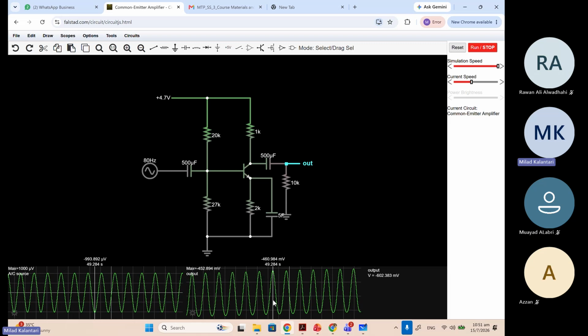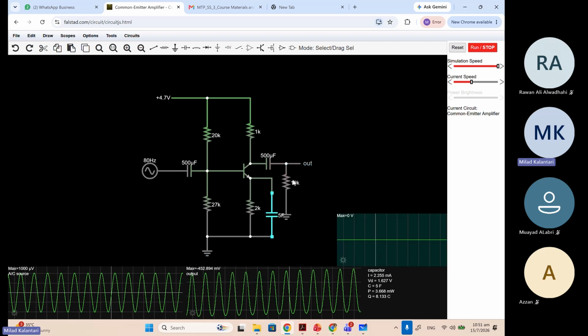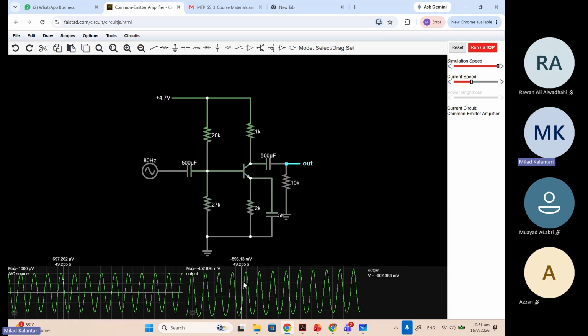So actually the DC may still not have settled down as we expect. You see that this is not DC, in fact, it's under the transient situation. The collector current at the moment is higher since it is not settled down, so the gm is higher. Maybe that's why the gain is higher.